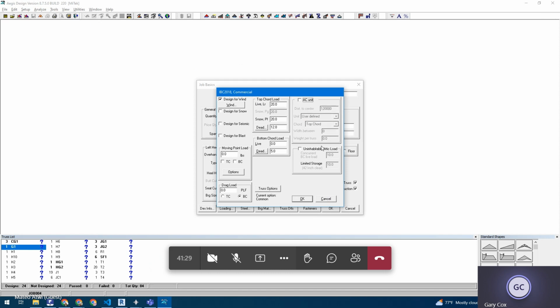Right. Okay, so you probably wouldn't even apply this in the job, right? No, unless you're doing something small. Right. Hey, we're doing this addition, and the AC unit could go anywhere in the building. You're doing all the same truss, so you would apply it to all of them, just for simplicity's sake. And then you have this uninhabitable attic load. What that is, kind of like the old residential use, is do you think they're going to stick stuff in the ceiling? That's what that's for.